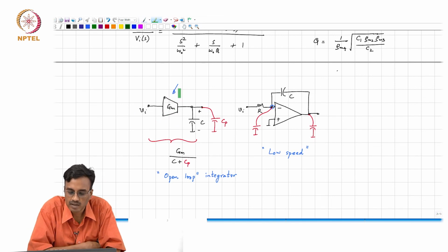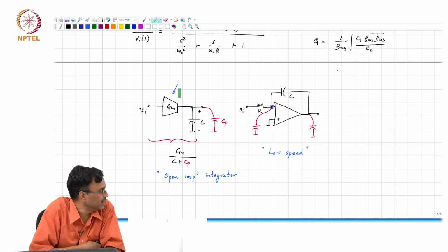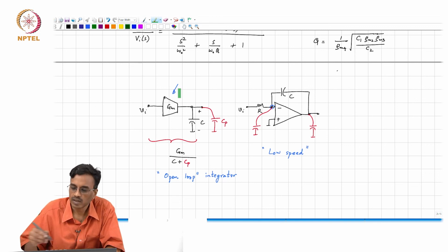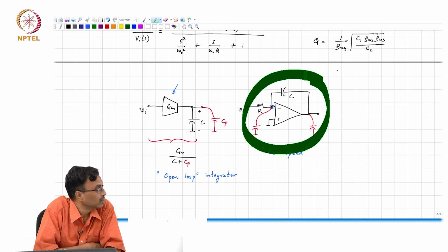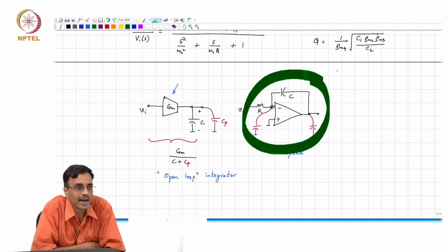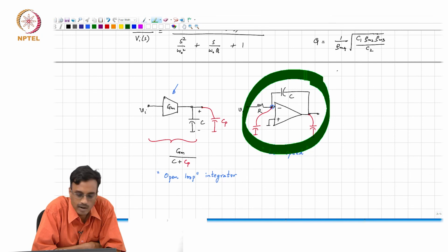If you want a very highly linear filter, but the frequency of operation is somewhat low, then you make this choice. If you want to make a very high frequency filter and have extremely high linearity, you sign up to do a PhD. So that's the trade-off between both of these.